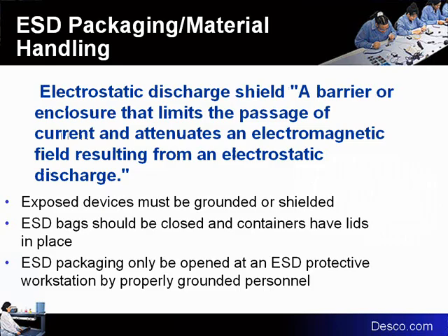The electrostatic shield is what gives the protection from any discharge. When the item is placed inside a metallized bag and the bag is closed and sealed, the operator can then disconnect from the wrist strap, carry it, transport it, place it in inventory, or move it to its next task. But before the bag is opened, it should be at an ESD protected area. The operator would have a wrist strap. As soon as they touch the bag, any charge on the outside of the bag would be brought down to 0 voltage and it would be safe to remove the device.